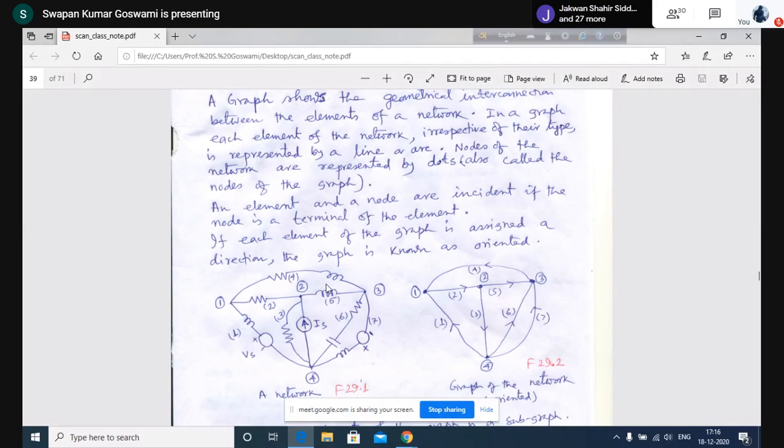equivalence between the nodal admittance matrix for this network and the product A, Y_B, A transpose obtained from the A matrix and branch to branch admittance matrix. You will be in a position to identify that. If any confusion, I shall show these things next, but I shall have to write, multiply, and then show you.